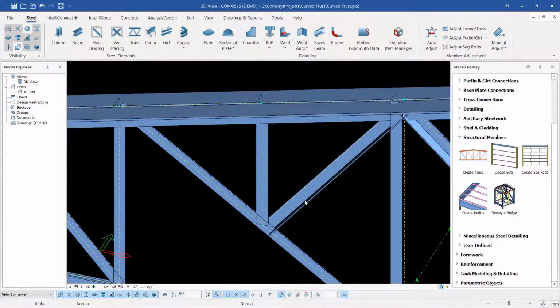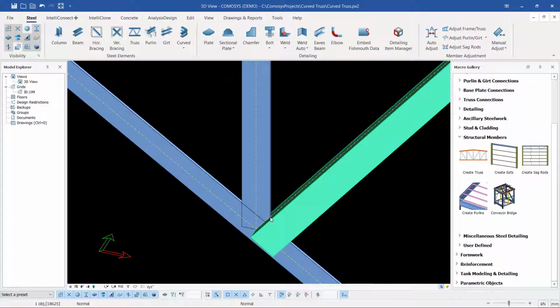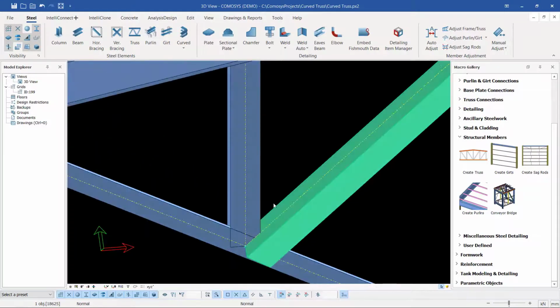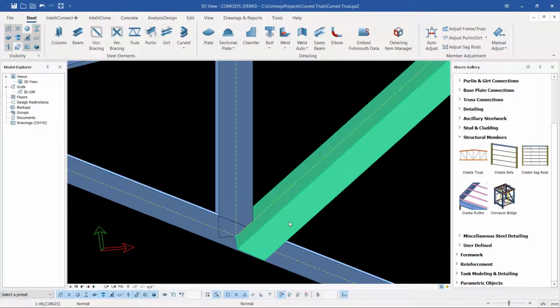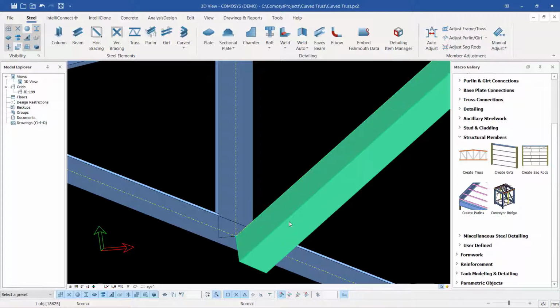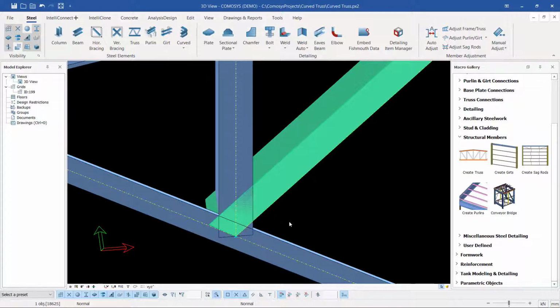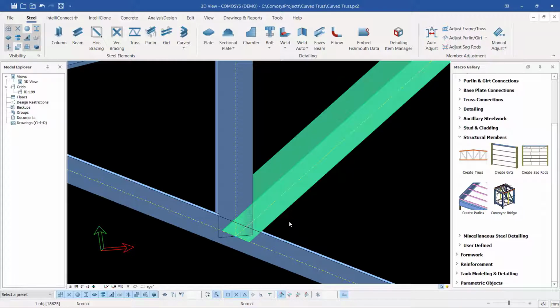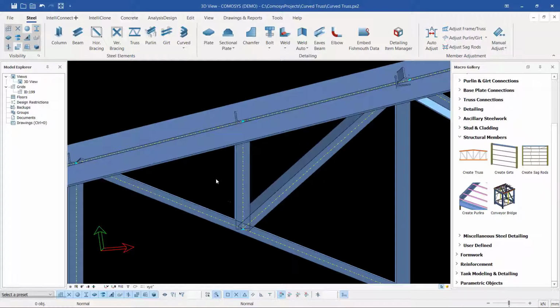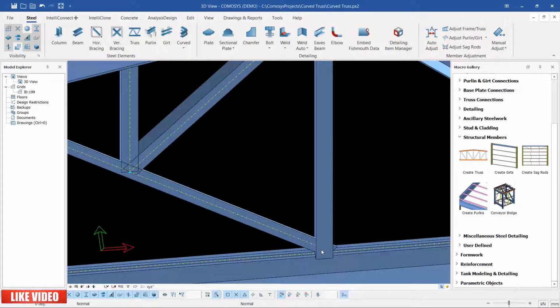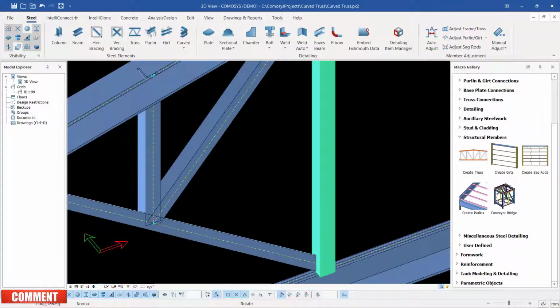So on this section, we now will go to Control Q to rotate this member. We want the back end to be this side. So we'll turn that round here. You can see that. So we'll press Control E to take it inside, and then press Control W once again. So you can see that it has brought itself in the best position of our preference.